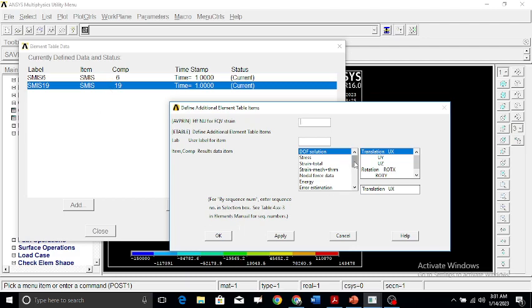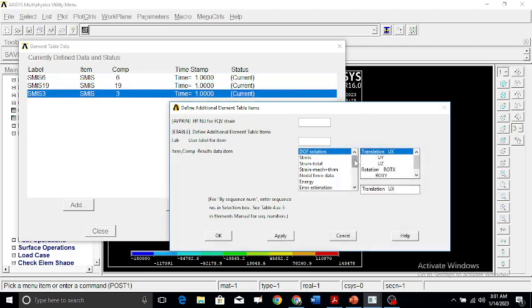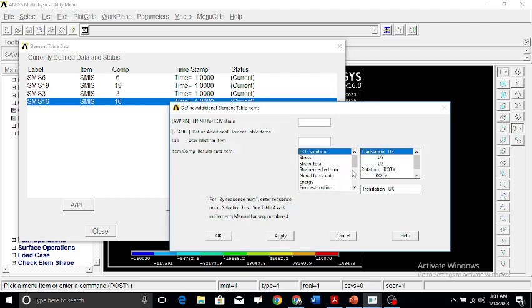Then you will again go and you'll be interested in the bending stresses of your beam. So now for the bending stresses, you'll be applying it as 3, and then you can again go and you can see you'll be applying for another one, which is basically the 16. Then you will go again for that, and you will basically ask for the bending stresses. Let you know, this 3 and 16 are for the bending moment about the z-axis. Okay, so this we are done.